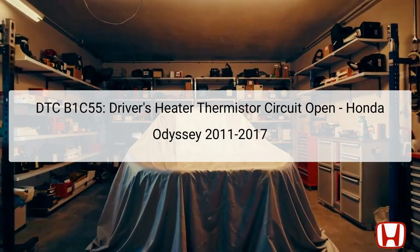The DTC B1C55 refers to an error indicating an open circuit in the driver's heater thermistor. This error commonly arises when there is a disruption in the electrical connections related to the seat heater system in the Honda Odyssey models from 2011 to 2017.